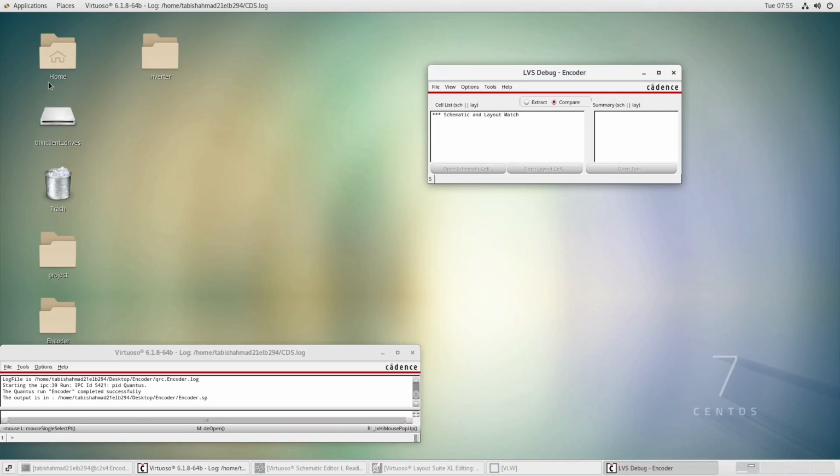What we are trying to do is add the resistances and capacitances that come due to the layout structure, like metal lines and the diffusion region, silicon, everything causes the formation of resistances and capacitances. So we need to extract a file of those resistances and capacitances. So we are trying to do that. So let me try it again.